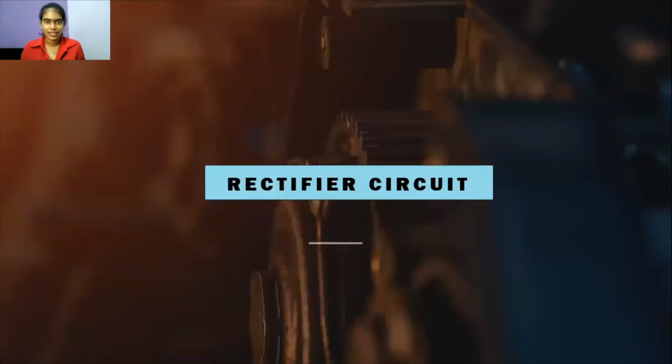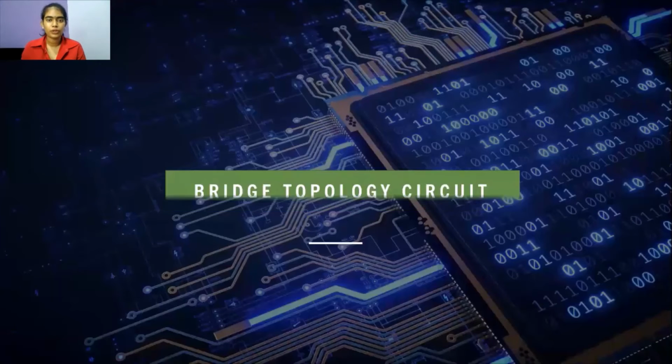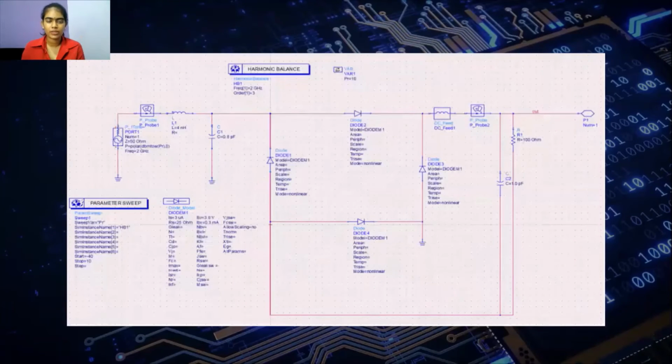Next, rectifier circuit. As we know, this is in ADS. As I mentioned earlier, 4 diodes, lumped element and also resistor. Bridge topology circuit, this is the simulation of energy harvesting with the rectifier. And that is P1, which is power transfer, which is to replicate the antenna, as in ADS there is no component for antenna.